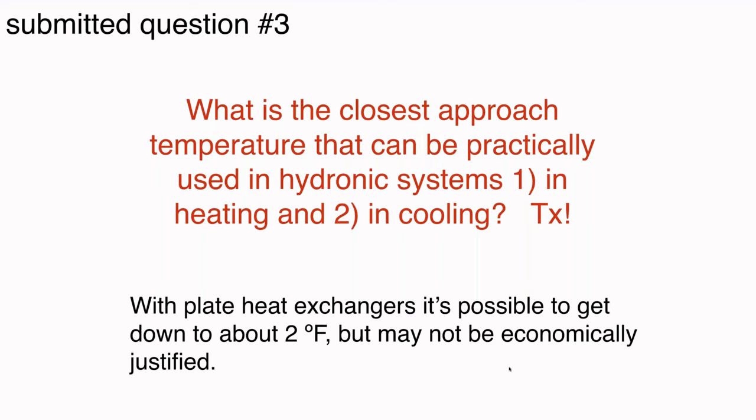In the case of a heat pump, transferring heat maybe to a fluid, an antifreeze, yes, the COP in theory would go up a little, but is that going up a little worth another whatever $1,000 on the heat exchanger? So again, you can't necessarily say I always want to design a heat exchanger for a 2 degree Fahrenheit approach temperature difference, absent consideration of what it is that you're accomplishing with that very close approach temperature difference, and what it is costing you to accomplish that.